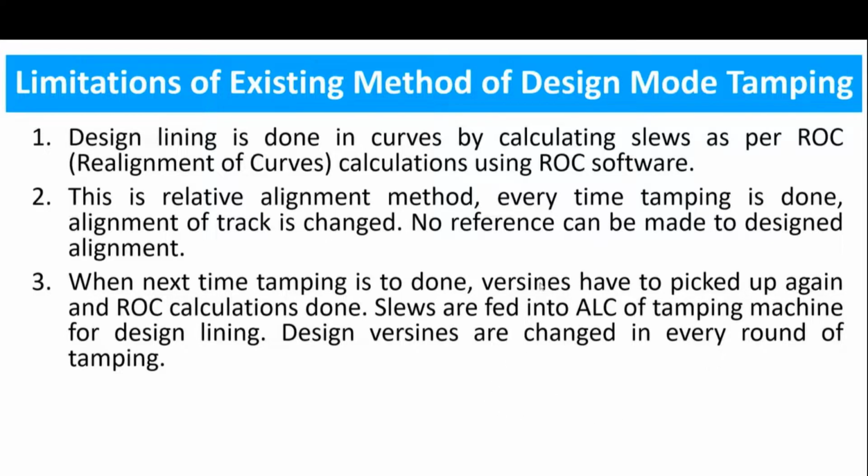When we have to do the tamping again, in the design mode, again we have to pick up the versines, do the calculations and feed the slews into the PLC of the tamping machine, and in this method the design versines are changed. Every time we do calculation, we change the design versines. In fact, geometry of the curve is changed.